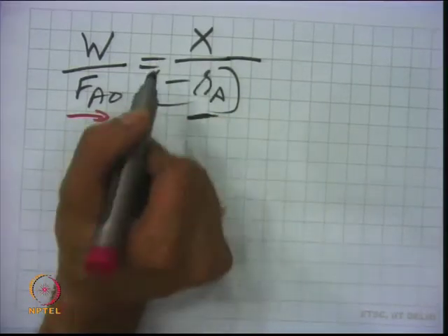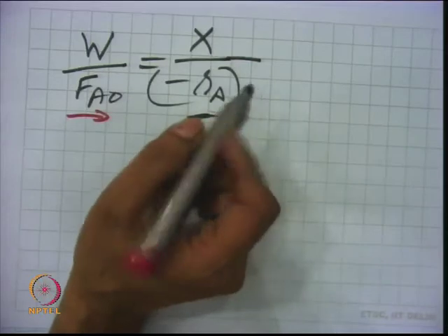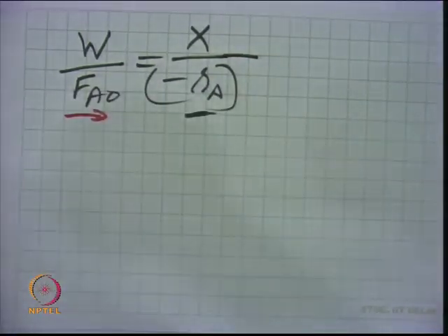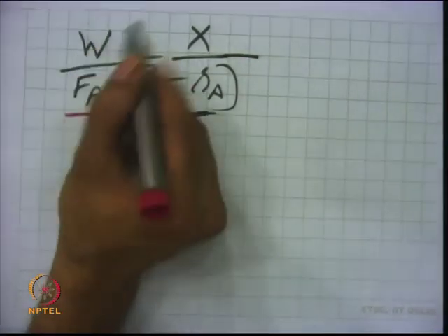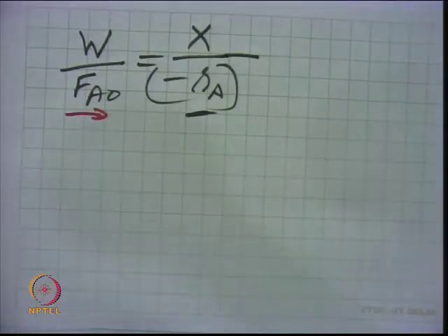But simultaneously one needs to check the distribution of the particles, because the W we are talking about is not for a fixed bed reactor, nor a moving bed reactor, but the particles are in a bubbling condition. So, there will be voids. We need to look at those conditions, and depending upon that you have to find out the degree of mass transfer and degree of chemical reaction, because every step will have its own resistance.